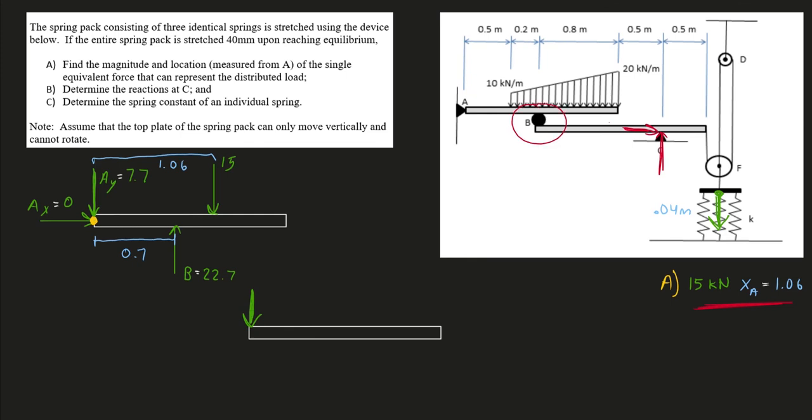It's only going to put a force, really it's going to have to be down. It can't even be up. This tension here, ropes can only pull. It has to be downwards as well. No x forces here. Therefore, this Cx must be 0. So really, I'm just going to write a Cy here, and then I'm going to write a tension T from that rope.